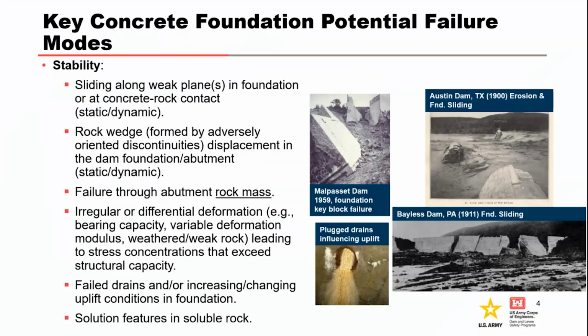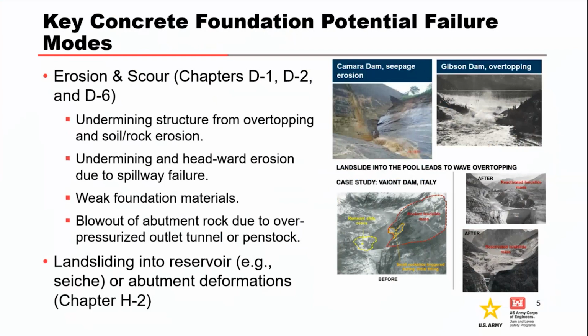And then failed drains or increased uplift conditions in the foundation. That's often a contributor to the failure modes that I listed above, and solution features in soluble rock. In addition, we consider failure modes related to erosion and scour during spillway flows or overtopping that could result in sliding stability issues. So I have a couple examples of Gibson Dam overtopping in the upper right.